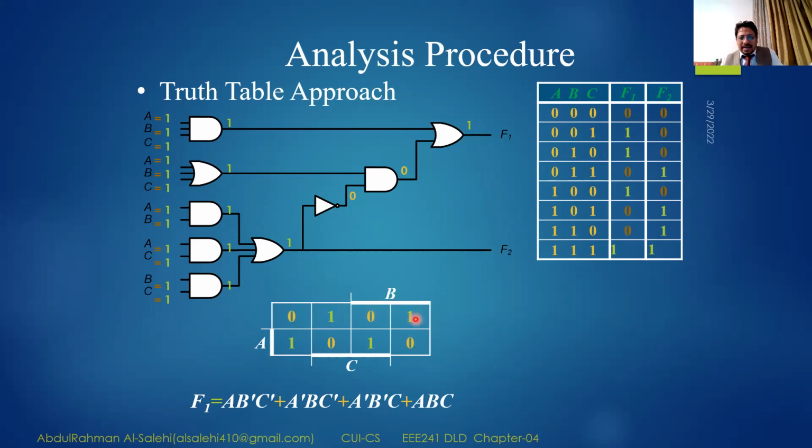Just when I have it like this, it's another easy way to build your Boolean expression, which we have done through the simplification of taking the values from each output. You can again get the same result here by using the Karnaugh map. Simple, very, very easy things. I mean, what you have to do is solve your functions in one of two ways. The first one is the Boolean expression, where you go through the mathematical model as in chapter 2. The other one, which you solve by taking the Karnaugh map, as you have done in chapter 3.